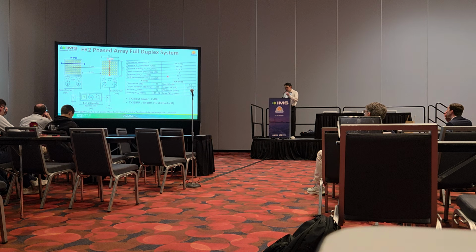So this is a split system. We studied from the 8x8 phased array system developed by UCSD. This is the RX phased array, and this is the TX phased array. For RX, we're going to use the H port, and for TX we're going to use the V port. They are separated by 7 centimeters, and the gap between these two arrays is 3 centimeters.